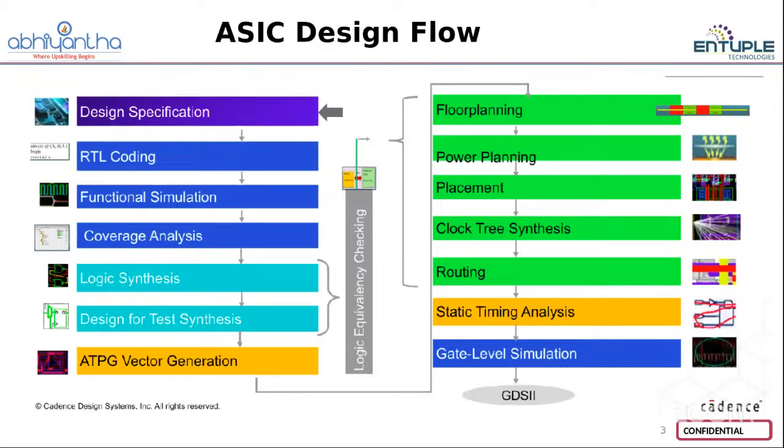So as we mentioned, here you can see that the entire process has been extended with the DFT process. Logic coverage analysis will be there, and design for test synthesis will be on the synthesis side. Generally we do the logic synthesis phase, and once it is completed, we develop the gate level netlist.